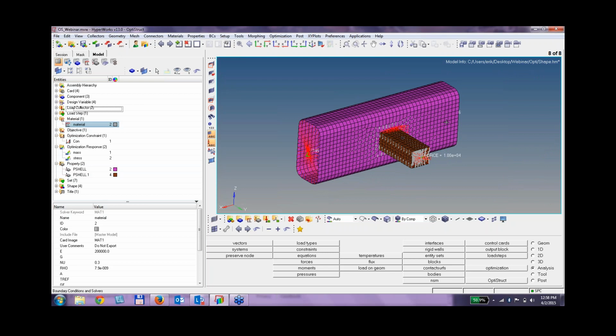You do have the ability to add non-structural mass to adjust that, but by default it will calculate all the inertial properties for you as long as you set up your model correctly with the correct shape and the correct material. It should be a pretty accurate inertial property on your model.